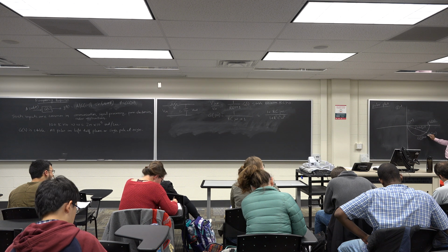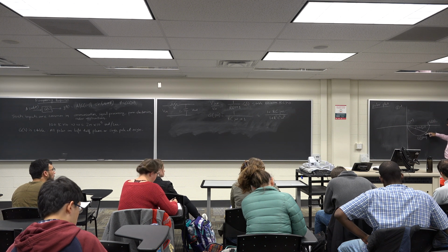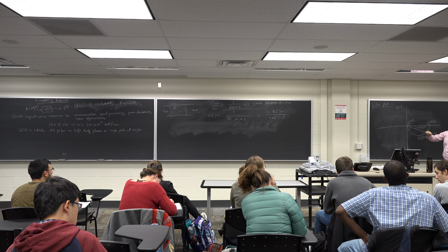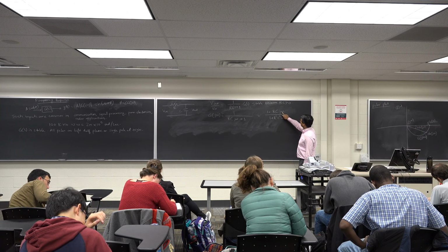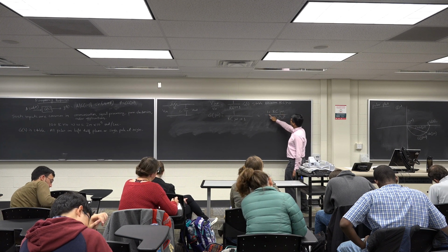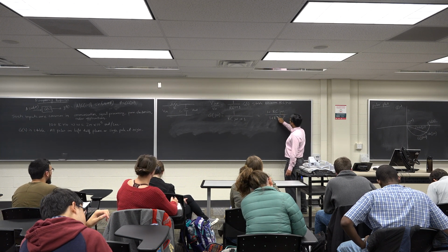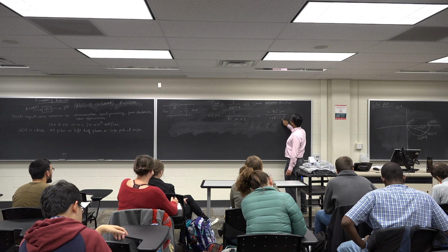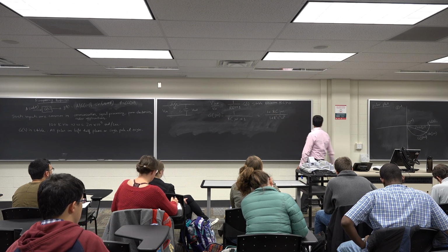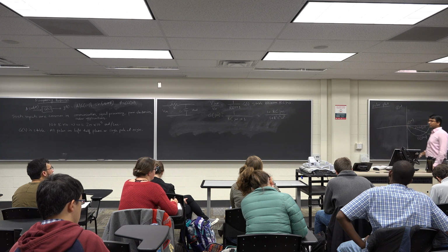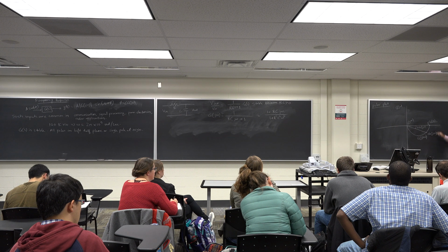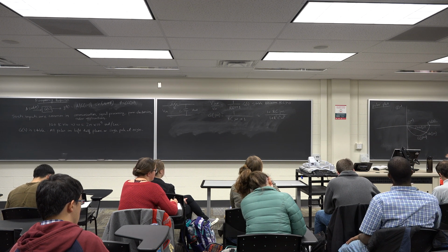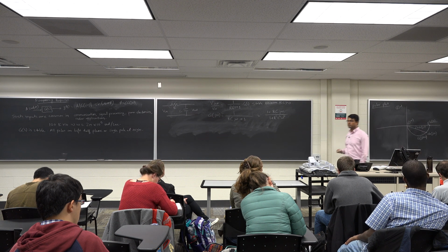As I increase the value of omega, I trace this semicircle, and when omega is very, very large, close to infinity, the real part is equal to 0 and the imaginary part is also equal to 0. So you reach the origin when omega is large. That's why G(j infinity) is at the origin. This is the semicircle for the first order system, and this is known as a polar plot.